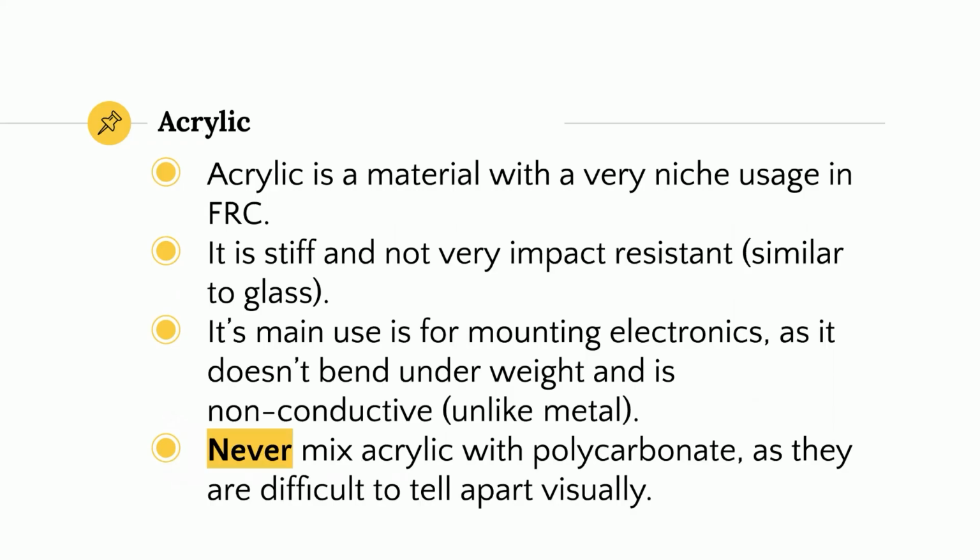Acrylic. Acrylic is a material with a very niche usage in FRC. It is stiff and not very impact resistant. This is similar to glass. It's slightly more impact resistant than glass is, but it should be thought of as basically glass. Its main use is for mounting electronics, as it doesn't bend under weight and is non-conductive. Essentially, if you don't want any risk of short circuiting, using acrylic as a place to put your electronics is actually pretty good.